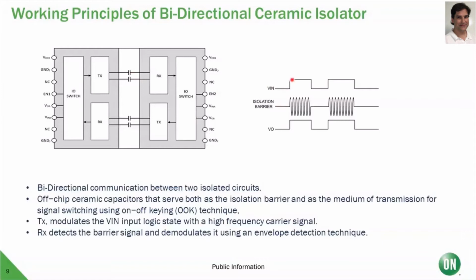When the input goes high, the capacitor is modulated and the signal is transferred across the isolation barrier, and you end up with a change in logic states on the output. This is showing positive logic, but we also have the opportunity to do inverting logic as well. And this is called an on-off keying technique. And again, it's common in the industry.